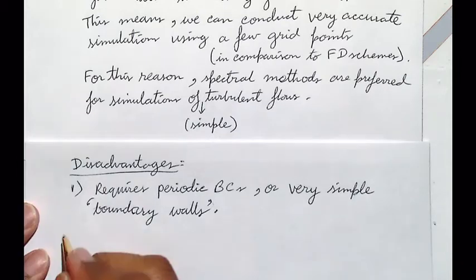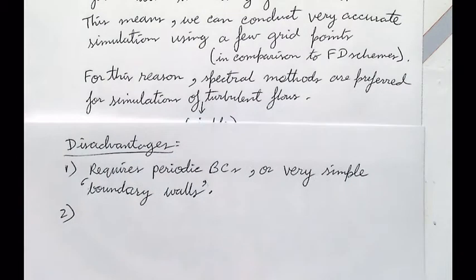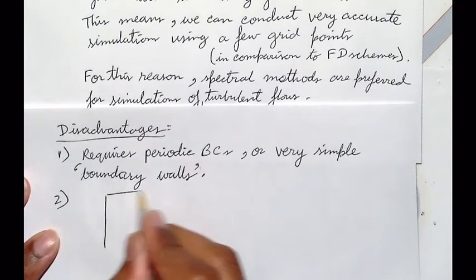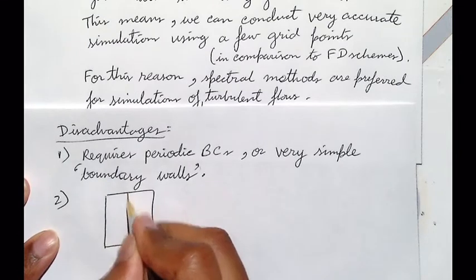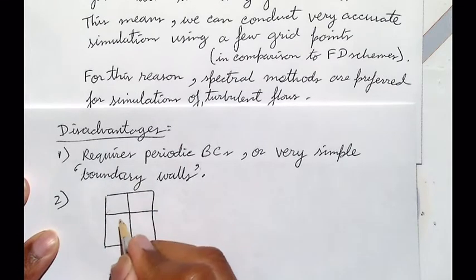Another thing is, if you remember some of the simulations we saw, the grid cells were not uniform. You put down more small-sized cells in regions where things are happening, and you take away cells from regions where things are not happening. So that's non-uniform grid cells.